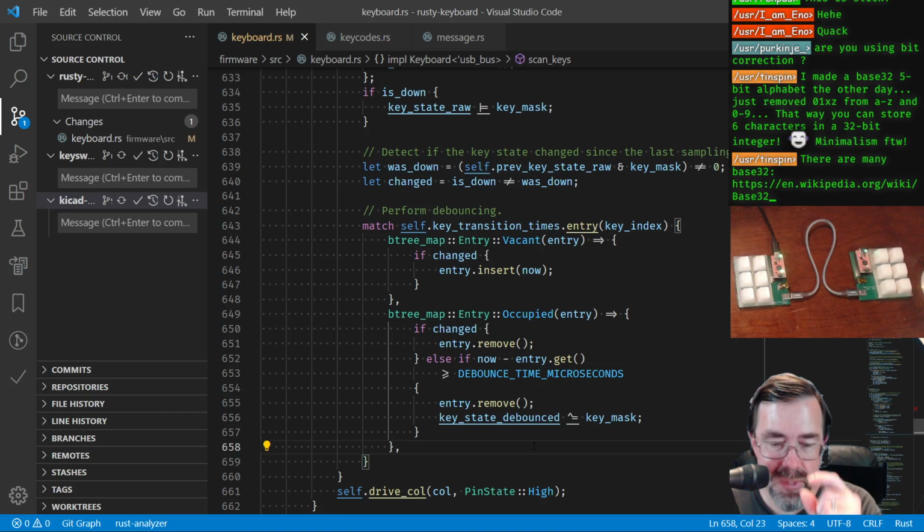Right on the edge of when the key is pressed and not pressed, there can be noise because of arcing of the current, and there could also be current flow, right? Voltage doesn't instantaneously change from 0 to 5 volts or whatever. There's a very fast but greater than 0 amount of time for that to happen. So that's called a bounce or a glitch or a bit error, however you want to call it.